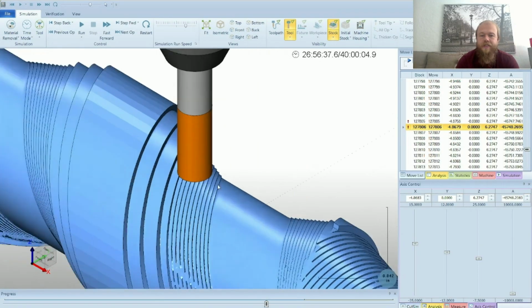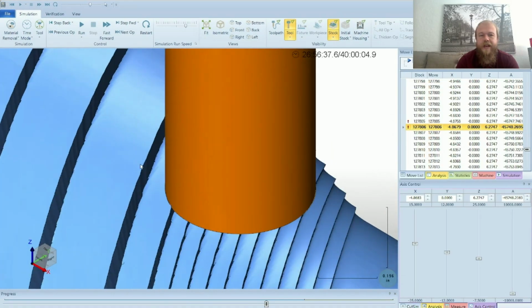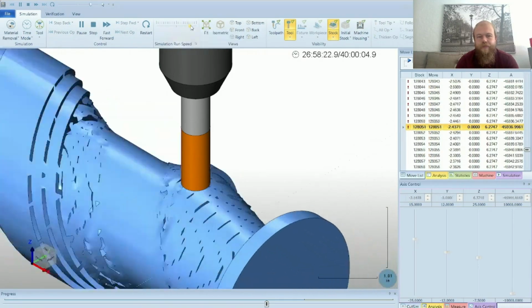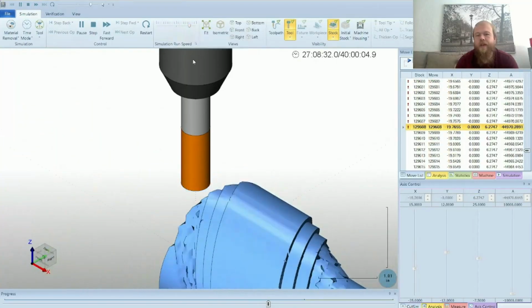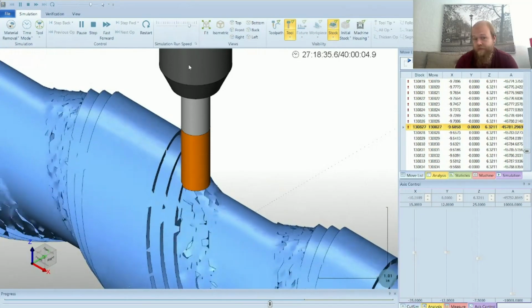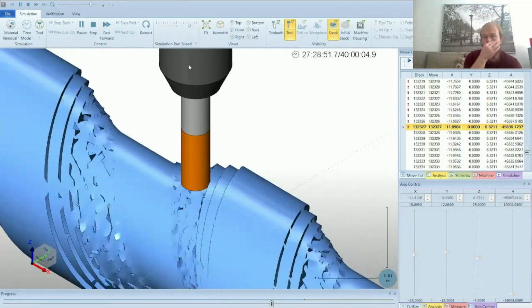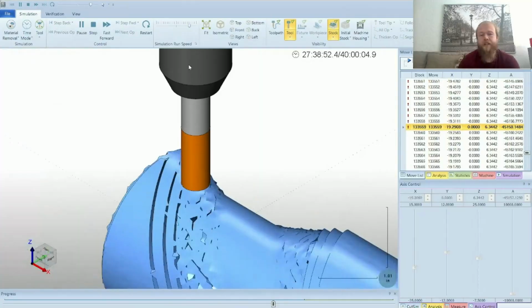The number of intermediate steps is where it starts at the bottom here and works its way up. This is 1, 2, 3 steps in between each one of these 100 thousandths as it works its way back up the part. So that way, instead of 100 thousandths, it'll be what? 25, right? Because you've got 25 with 3 intermediate steps in between the 0 and 100 thou step there.